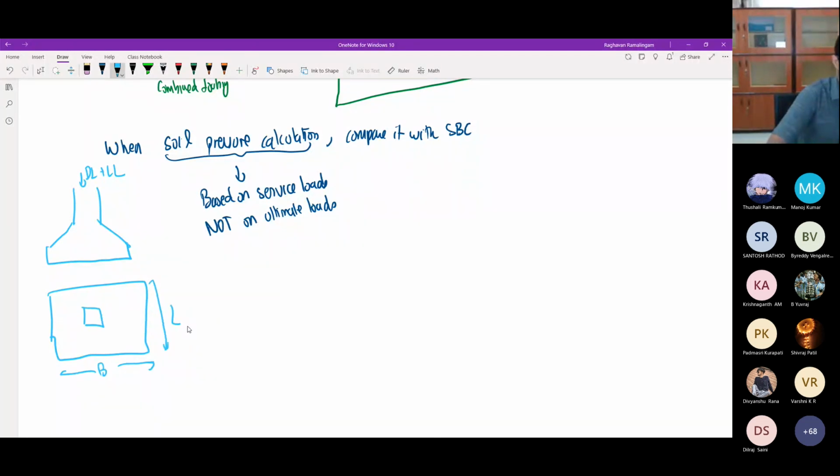So you're finding the pressure on the soil as your DL plus LL divided by B by L. Actually, let me not say DL plus LL, I'll just say P.